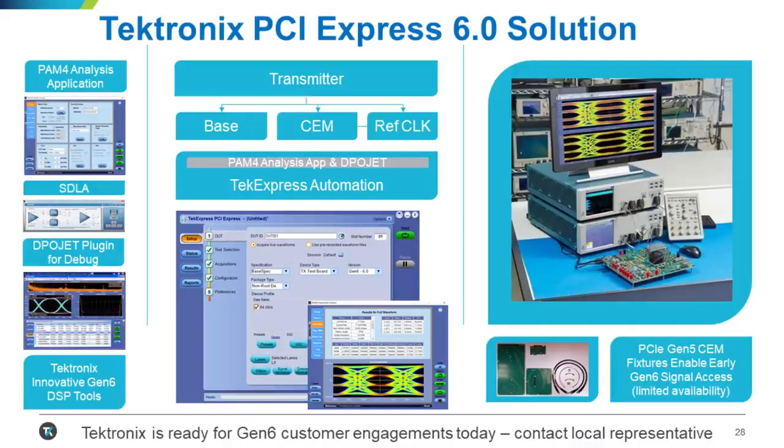Is SigTest going to be used for compliance on Gen 6 with all these new measurements, or are there some other tools that are allowed or used? Yeah, that's a very good question. I think it's a little bit unknown right now. There hasn't been a roadmap for a PAM4 version of SigTest provided publicly. I would expect that to come, but we don't know when that will be available to members, or broader than that, at this point.